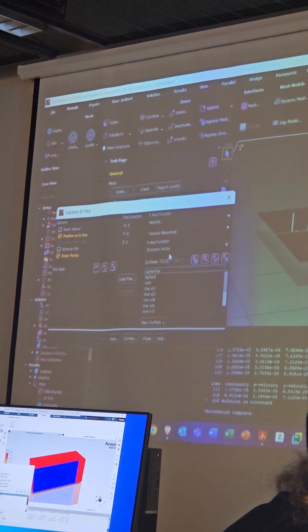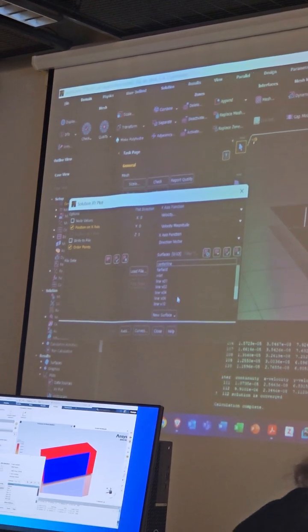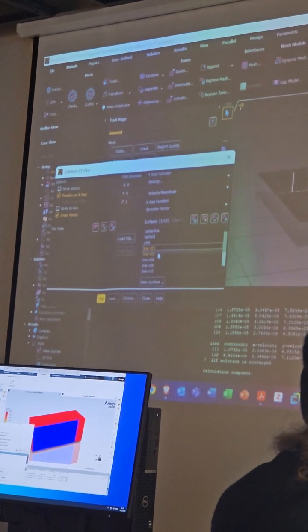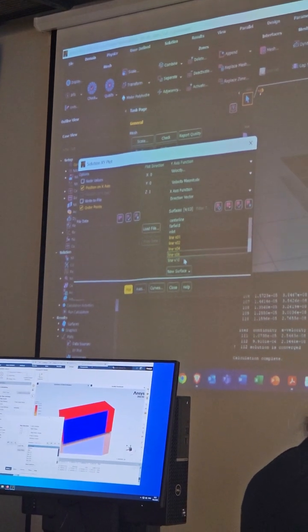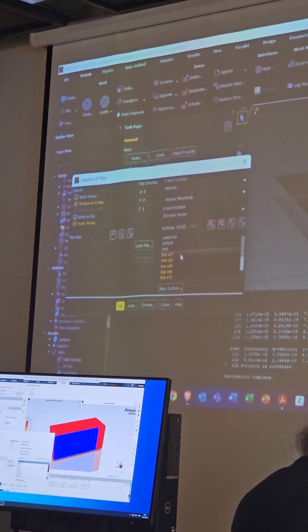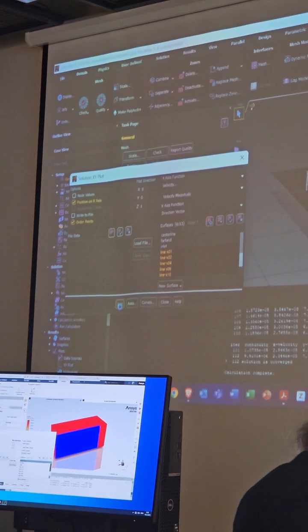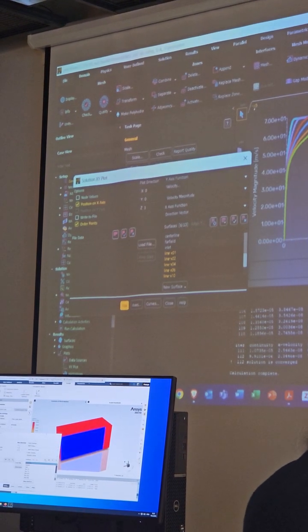That means the velocity is 0, the same velocity as the solid. But we want to plot the velocity at lines x01, x02, 04, 06, 10, and 15. So we select the lines perpendicular to the plate, and we can plot them to see that they look well.